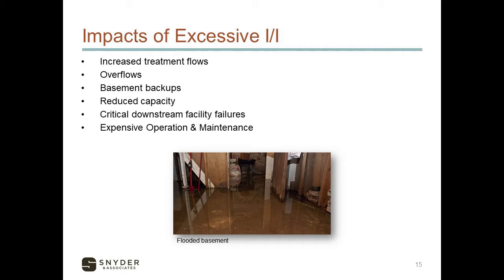This would include any pump stations. Say that you get into the comparison of having to upsize an existing pump station to handle the increasing amount of clear water, the I&I that's getting into our system that is requiring a higher capacity, or we can start looking at areas that we can rehab and hopefully reduce some of those priority areas to avoid having to upsize that pump station. Expensive O&M, chemicals to treat the wastewater, power to operate our pumps is really what that relates to.